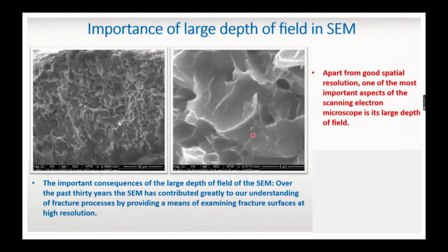Okay, right. I think somebody has given the answer after seeing the slide. Is it like that? Okay, fine, but it's good that somebody said at least. Over the past 30 years SEM has contributed greatly to the understanding of the fracture process. Whenever you are dealing with a fracture surface, you have to go for the SEM. It can give you a good examination of your fracture surface with very high resolution. Here you can see in a very good manner this lining and how this surface is looking.